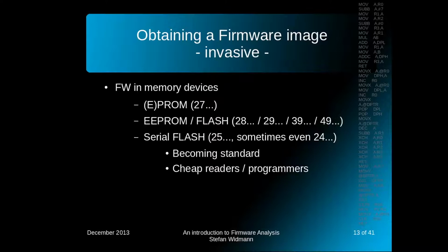We open the device and we search for memory devices on the PCB. If you have a very old device, maybe you will encounter EPROMs or even PROMs, 27 something. If it's a little bit newer, you might see EEPROMs and flash, 28, 29, 39, 49 something, and the big flash devices and bigger devices with 48 pins, for example, with various other names.